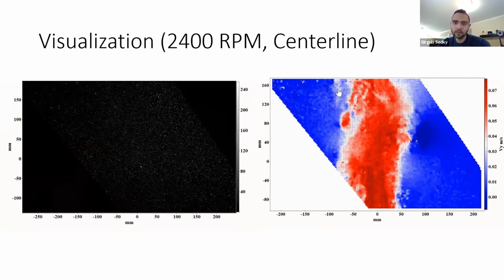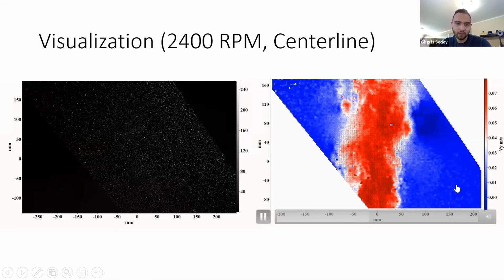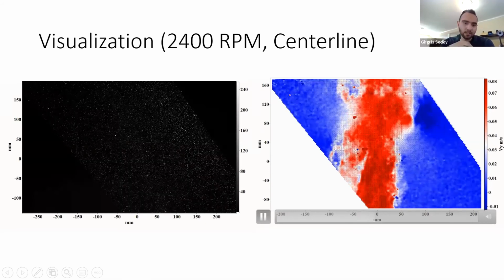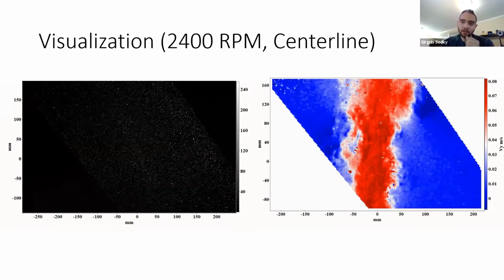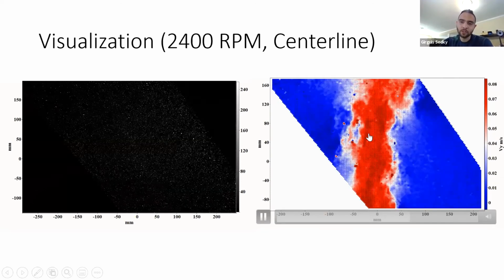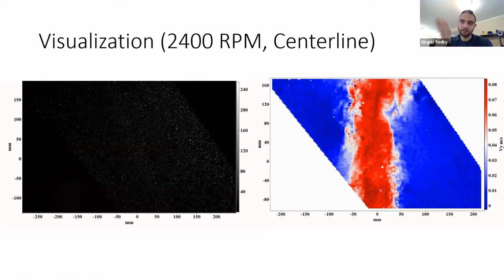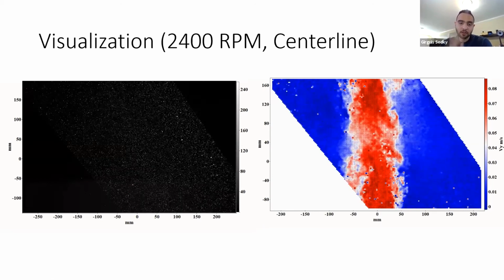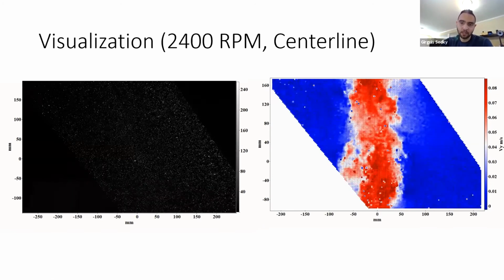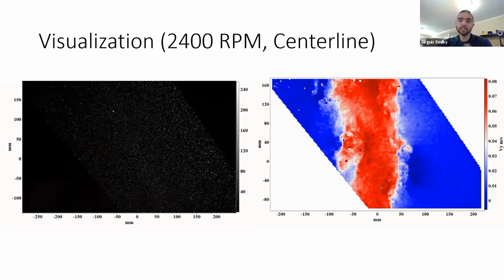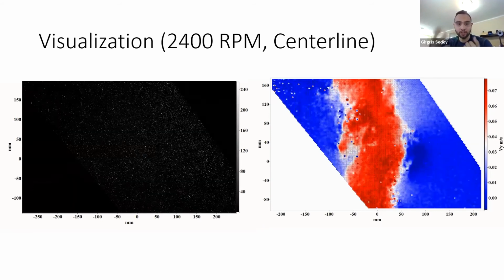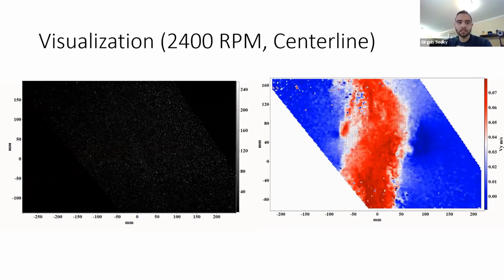So you can see that towards the edges of the gust, there is no flow, because we're operating in a water tank with quiescent fluid. But once you get in the gust region, you see lots of high vertical velocity because of the gust generation. So that's an example of a way we'd characterize the gust that's being produced.